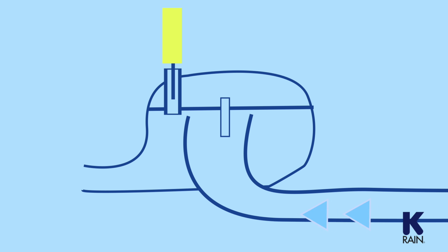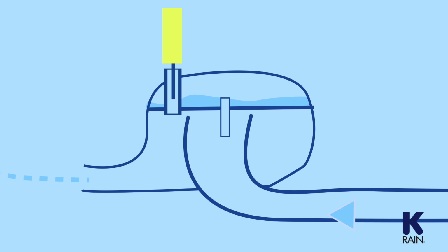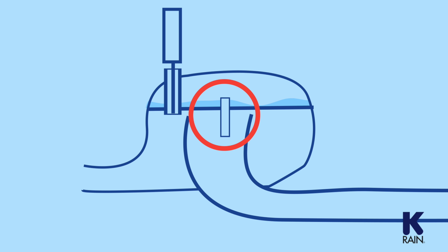While the valve is in operation, there's always water going into the chamber above the diaphragm. It just goes right back out the exhaust port. When it is time for the valve to close, the controller stops energizing the solenoid, causing the plunger to drop and seat on the exhaust port. This prevents any more water from escaping from the chamber above the diaphragm. Water still flows into that chamber through the metering system, but now it can't get back out.